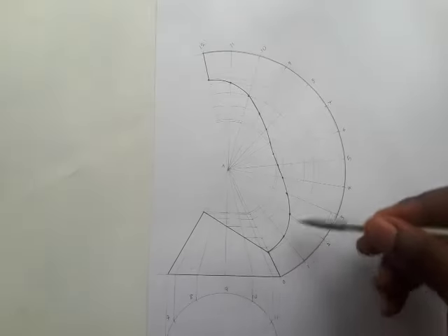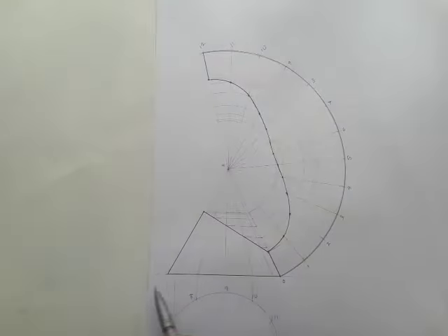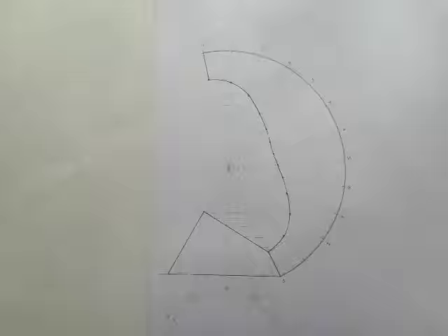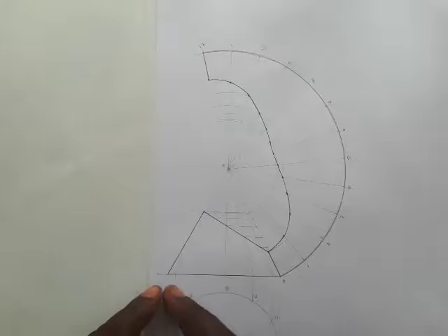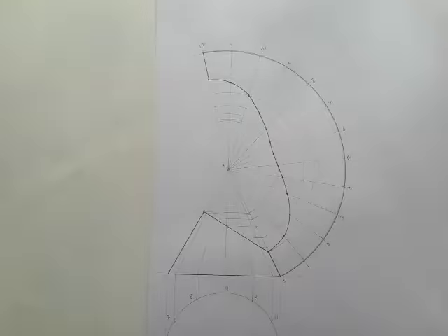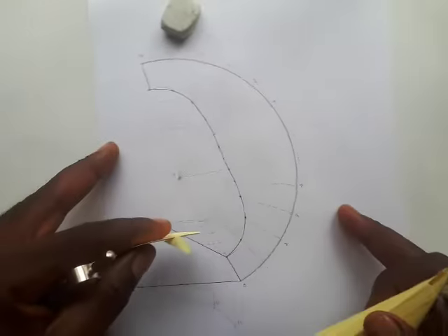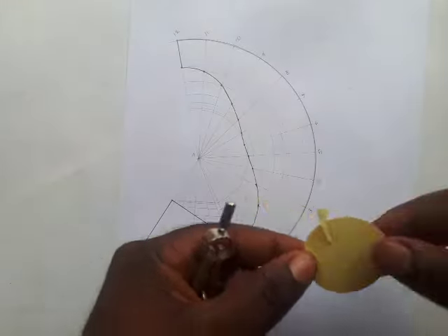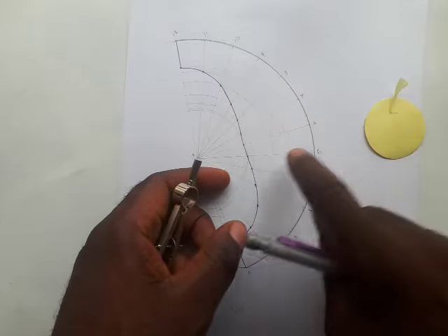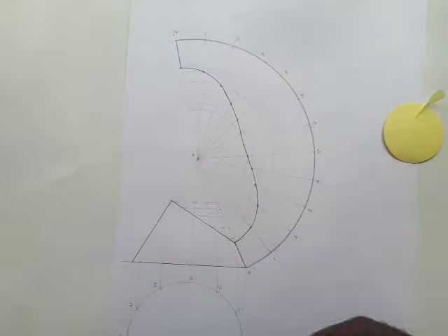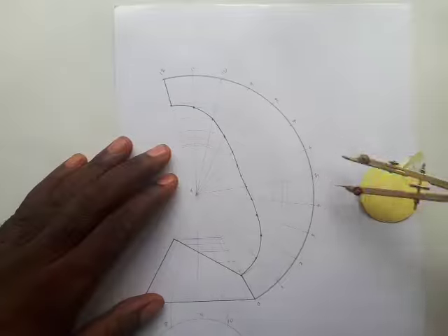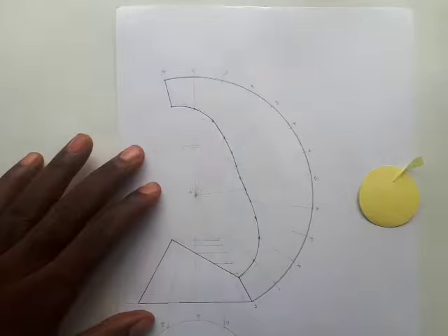Okay, so there you have it. This is the development. Once again, if it is an open cone, then this is just the development. That's all. But if it is a closed cone, definitely you're going to have the base of the cone. There's this covering. So you're going to have it somewhere here, anywhere. Just draw a line out and draw the base of the cone using the same radius you used here for this circle. So you draw the base of the cone. All right, so that's it.